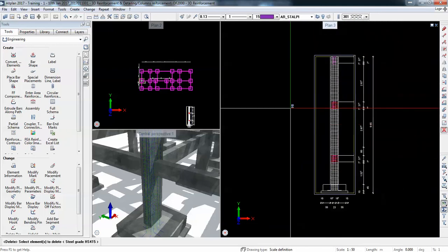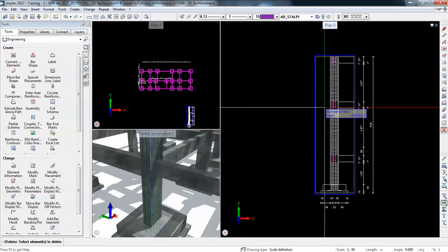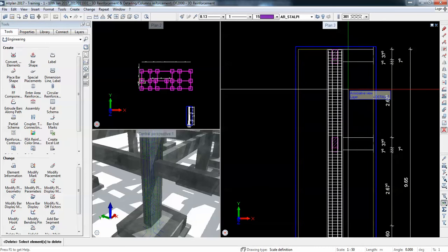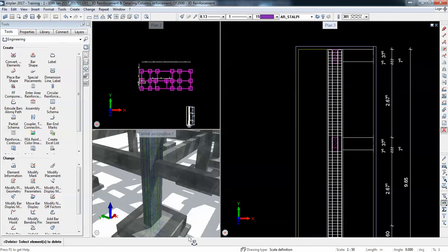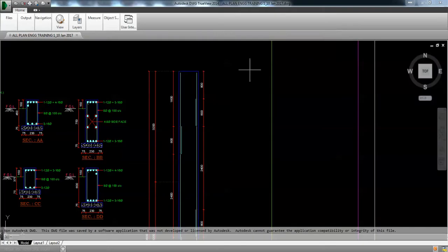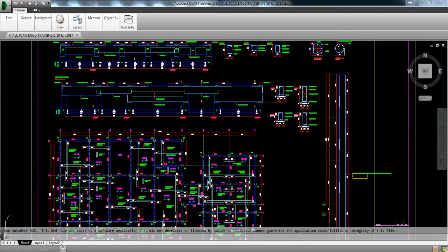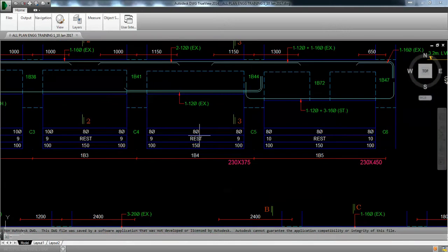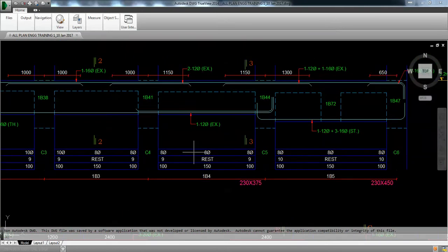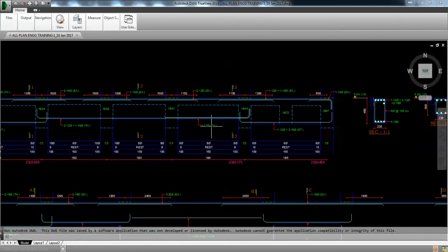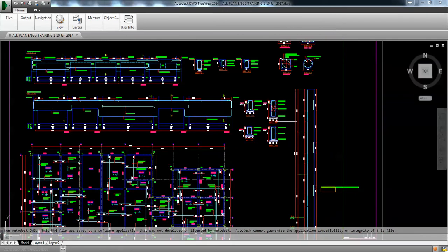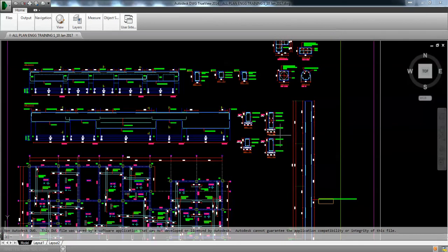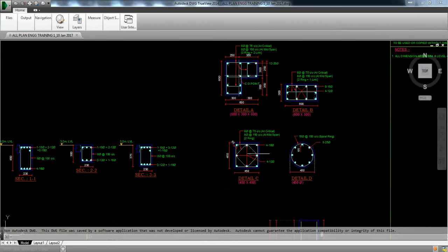So once I select nodes, I just right click and they are removed, and then I have to solve this issue because I need more stirrups where I have big forces, and less where I don't have shear force or plastic hinges, I'm not required to use as many stirrups.